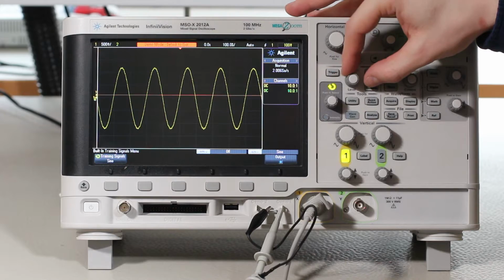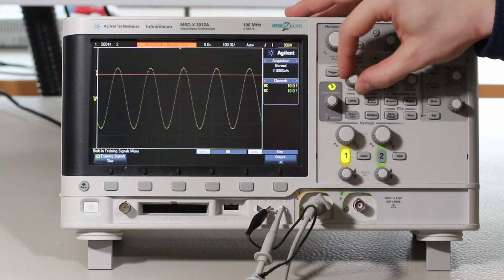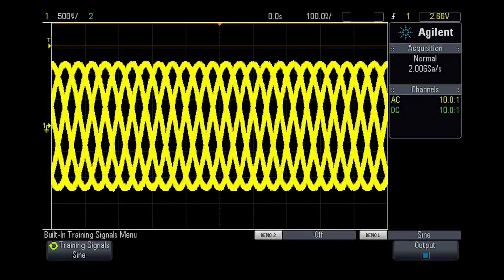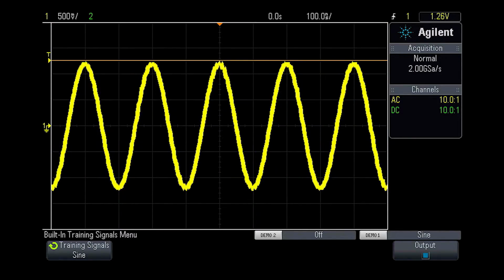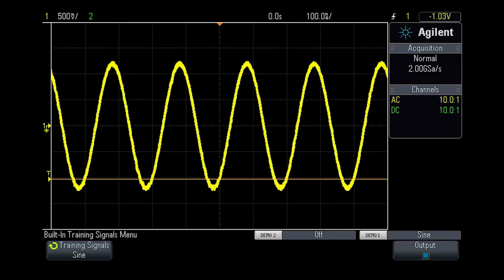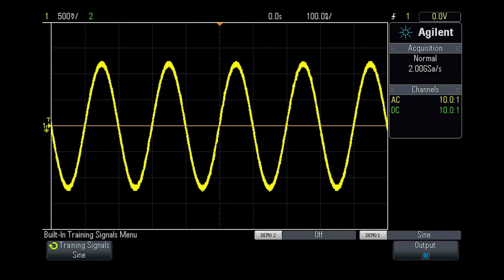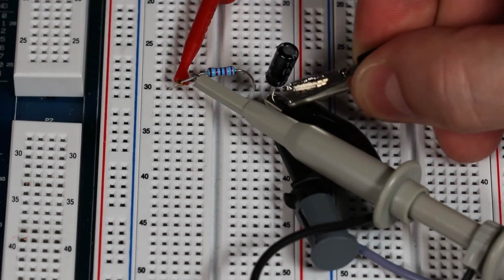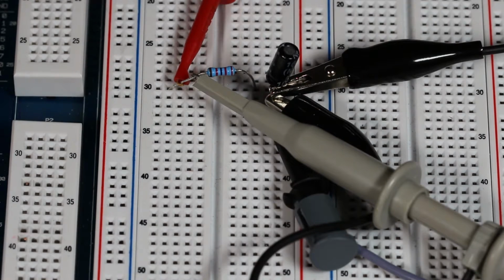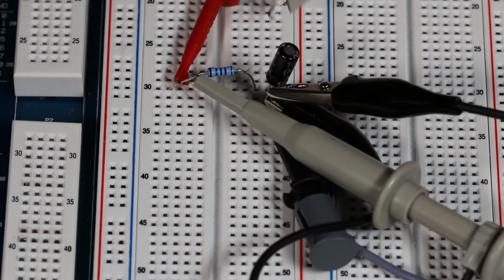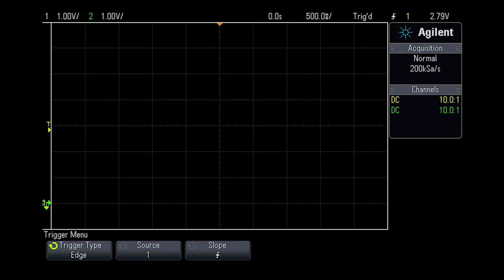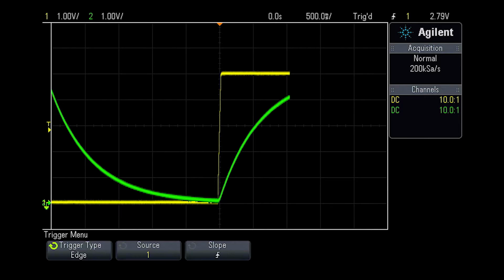The next common feature to oscilloscopes is the trigger adjustment. Basic triggering is used in 2 ways. It can be used to synchronize a repeating signal so that it appears static. The trigger dial changes the value on the upward or downward slope of the signal that is used to synchronize it to the display. In this example, a simple capacitor and switch circuit has 2 probes attached so that the voltage can be measured across the capacitor and across the switch as it's closed. When the voltage across the switch exceeds the trigger point, 0 volts, the oscilloscope starts capturing the signal.